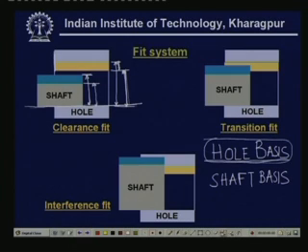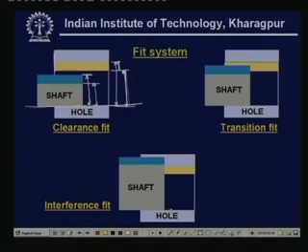Well, in this particular case, first of all, this is what we call a clearance fit. What is a clearance fit? Clearance fit means the shaft will be moving inside the hole in a loose sense, meaning there will be a clearance inside the hole. How is it being seen?